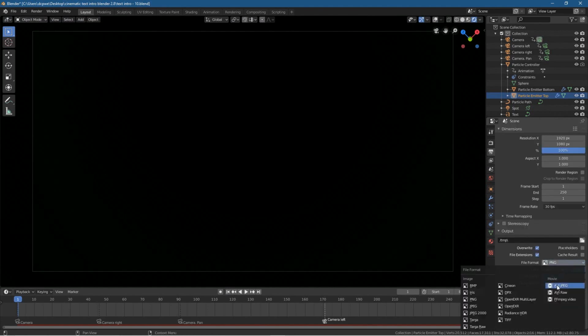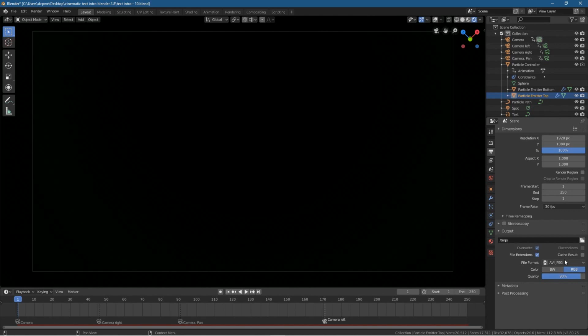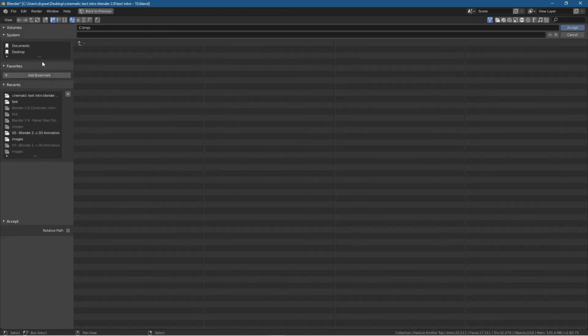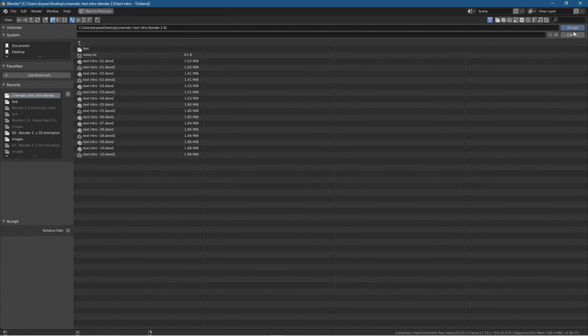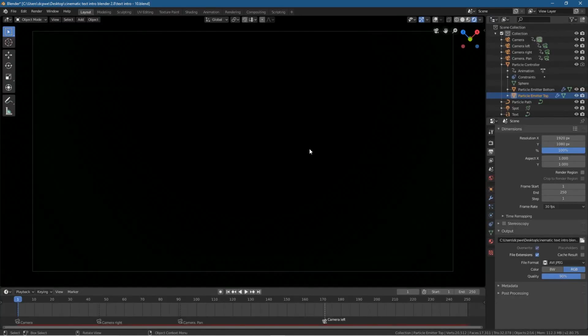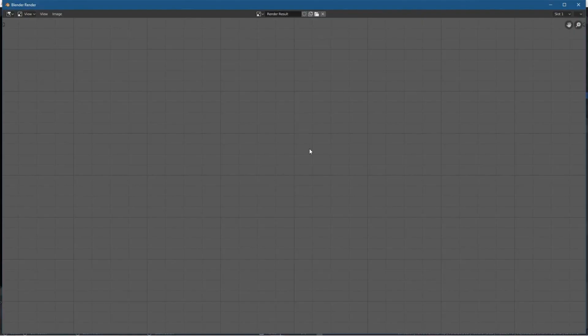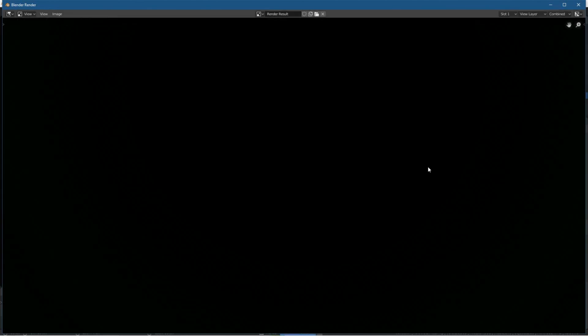Let's set this to AVI JPEG here. Let's click on the open folder. Let's go to my desktop. Let's go to here and we just click accept. And now all we've got to do is press Ctrl and F12 to start rendering out all the frames. So let's do that. I'm going to pause this video, and once it's finally rendered, we'll check out the final animation sequence.